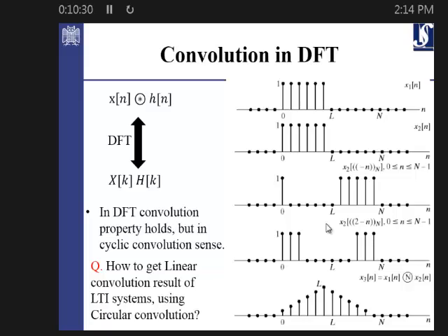What you do in the discrete time is that you keep the first one, which is actually at the origin, which is 0, and then you reverse everything inside that window. Inside the window means that the rest of the things should be mirrored, but from the end. So we are actually doing the mirror at the end. So this value now is here. This value is here, and so on. So this one is actually here. That's the way that we mirror the signal in a circular shift, circular manner, and this is the way that we represent it in mathematical form.